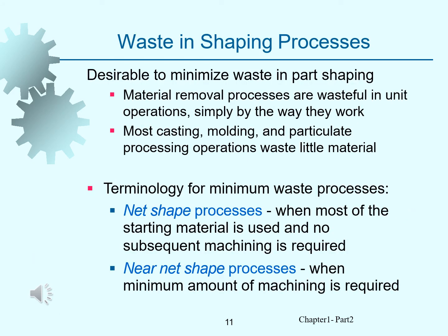We're going to talk about this in depth: waste. This is non-value added. If you're making scrap, you're losing money, so you want to minimize that, right? Casting, things like that. I worked for a company that made copper tubing, and they didn't realize how much money they were throwing away. They said, well, we remelt it so we really don't lose anything. But basically only about 20% of what they started off with made it to the end. So if you're doing that, you're wasting money, because you still have to heat it up again to remelt it.